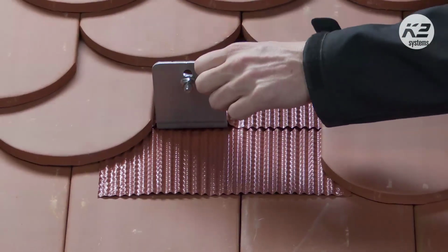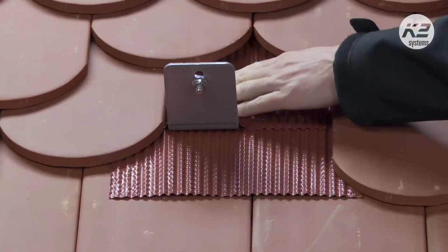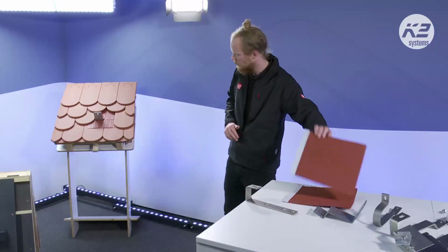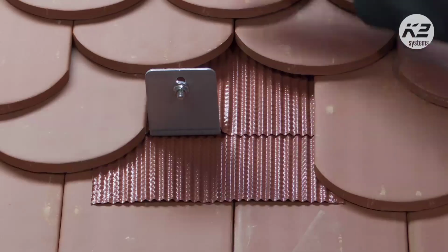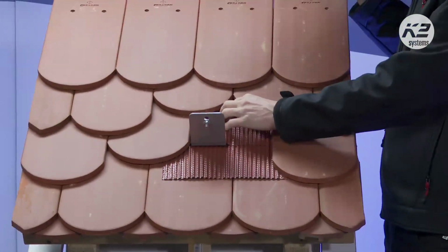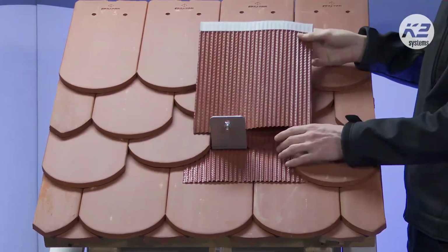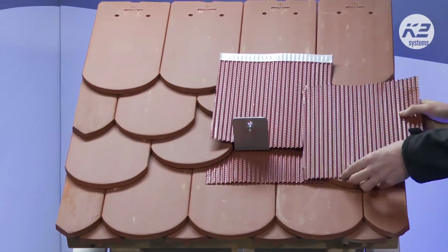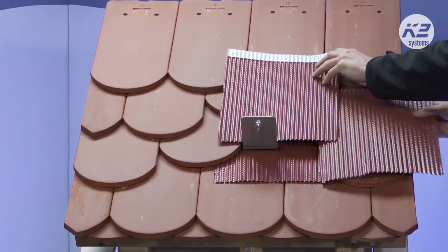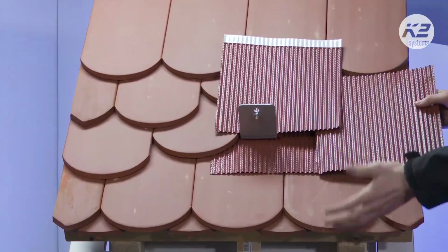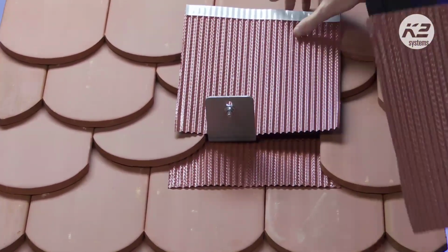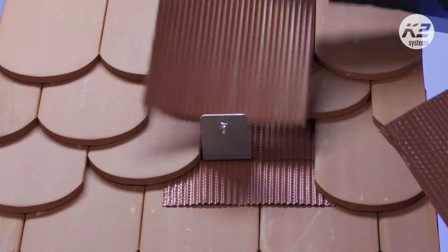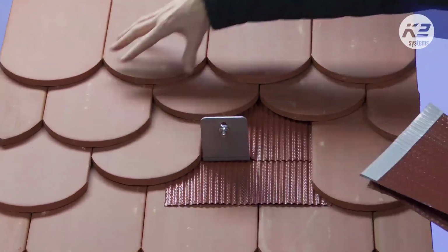We're fixing to the batten with our single hook. And then on top, we are going to place this sheeting for waterproofing, and underneath as well. So if there is any rainfall that's coming, it is just going to run down over. And this overlap is, as you can see here, quite substantial. Any rain that falls on top is just going to run down onto the tile below. You can see here this is also quite a large area. However, you will have to remove a few tiles around.